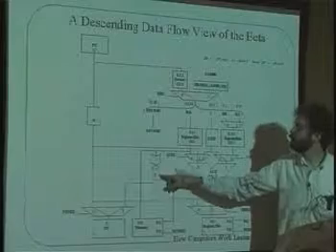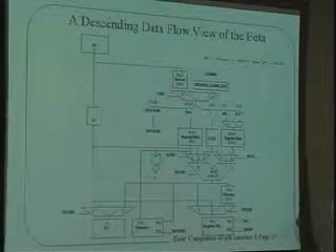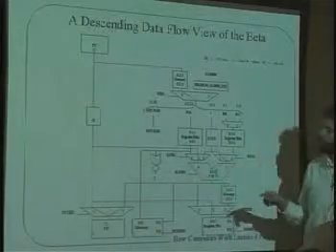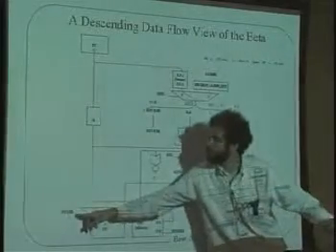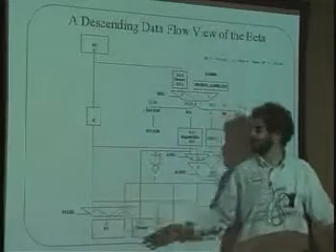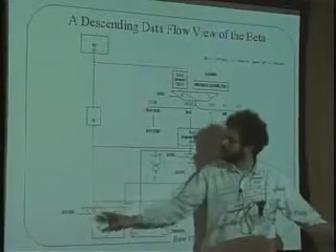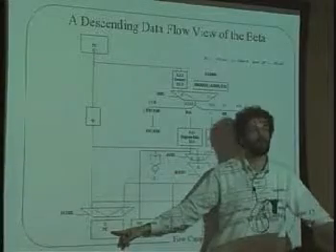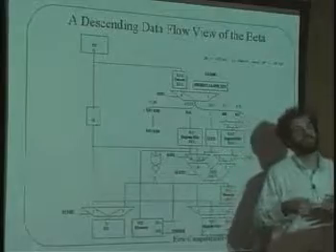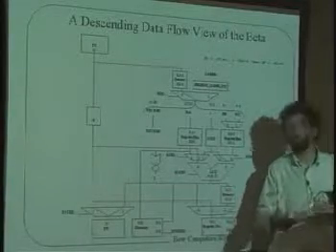And whether or not it's 0 will then control, through the same control logic that looks at the opcode, whether or not PCSEL gets set to 0 or to 1. If PCSEL is set to 0, then the PC will be loaded with what? With PC plus 1. And we'll just go forward to the next instruction. We will not take the branch.